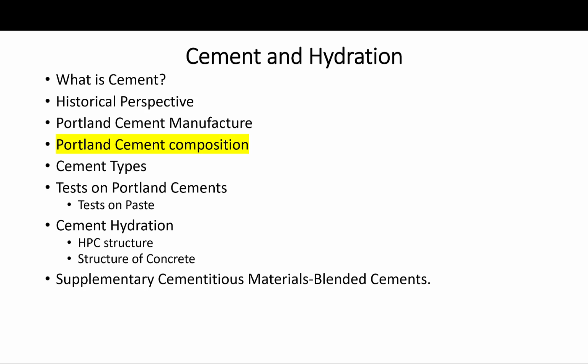Just remember, as I said before, the Portland name is really a generic name, and it is given to cement with certain characteristics that meets certain criteria. That is the ASTM C150. As mentioned before, the cement is the active component that reacts with water and creates the binder, which is the paste within the concrete matrix, and responsible for the strength gain over time.